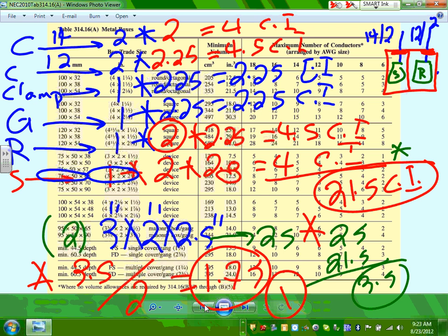But then you're going to change the wire, because you're using 14-2 now, or 12-2. Well, in this case, I'm bringing 14. It really doesn't make sense the way I did it. You almost have to bring 12 to make this a multi-wire branch circuit. So circuit up, circuit down, or an isolated ground receptacle. Then you have to take the 12-2, throw it out the window, and bring 12-3. That's when you add that little device. Does that make sense?